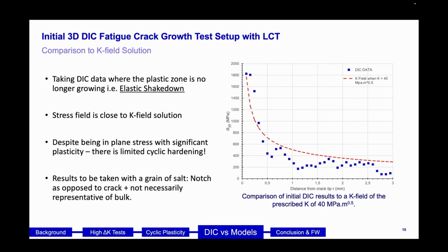We'll be at a point where you can, theoretically speaking, not really use a K factor nor even a delta J. So it's good to use stress, or at least a strain field, to compare, because that is based in reality. This is quite interesting, and I'll study how this evolves as the crack gets longer.